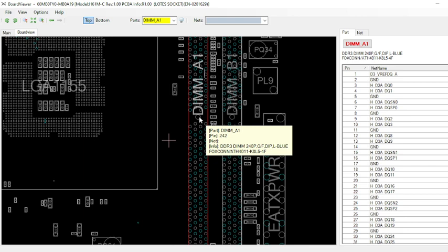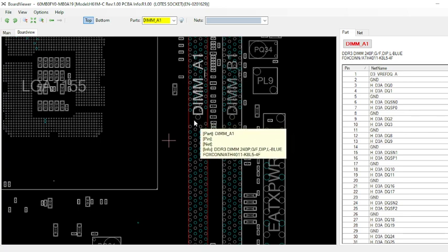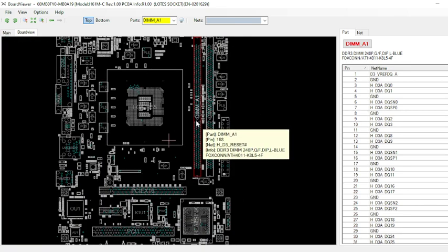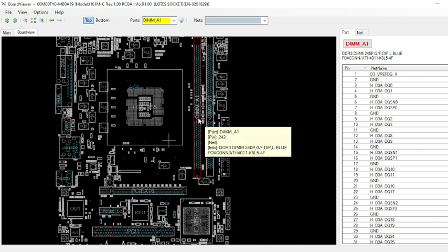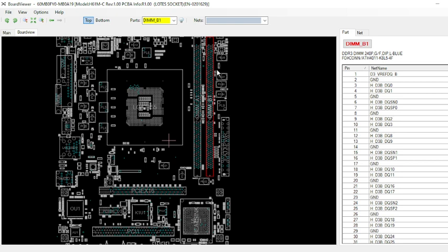If it is DDR4 it will be 1.2 volt, if it is DDR2 then 1.8 volt will be written there, and if it is DDR1, 2.5 volt will be written. From this operating voltage you can know which RAM is supported by that motherboard. But by default each and every H61 motherboard supports DDR3, and its operating voltage is 1.5 volt, so it should be written as 1.5 volt. Okay, so let's start with the RAM section.